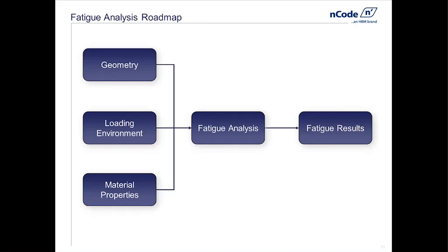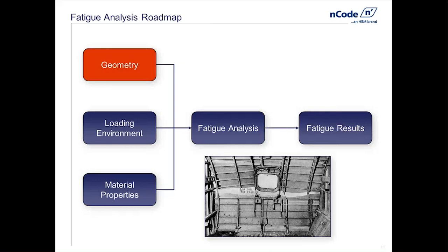First off, for geometry, what we mean is we need to understand stress concentrations. You'll find through our discussion today that fatigue hotspots are always stress hotspots. Fatigue, as a matter of fact, is like stress raised to a power. It can be quite a large power. So where stress is concentrated, fatigue damage is concentrated, and fatigue life is short.